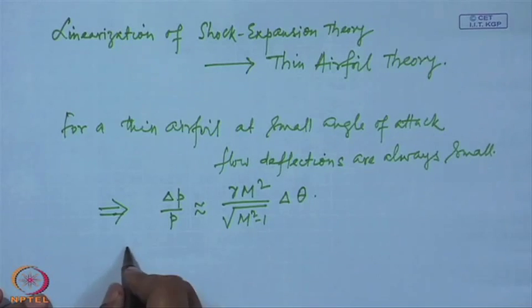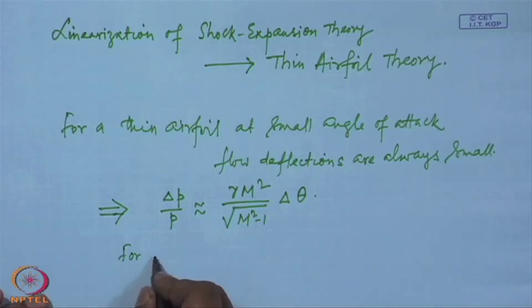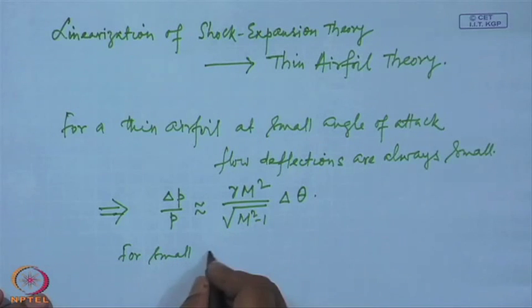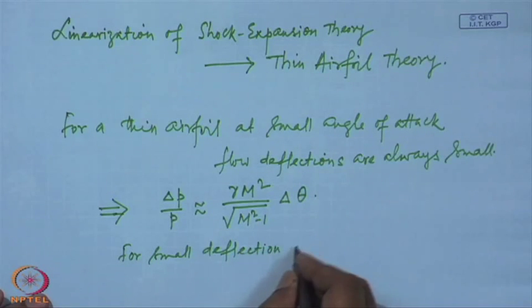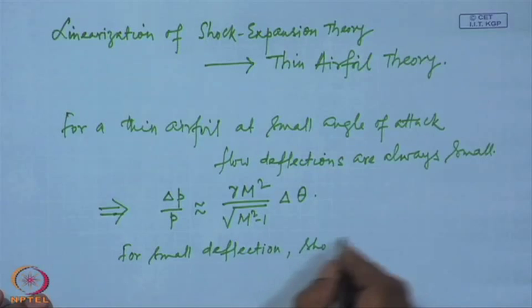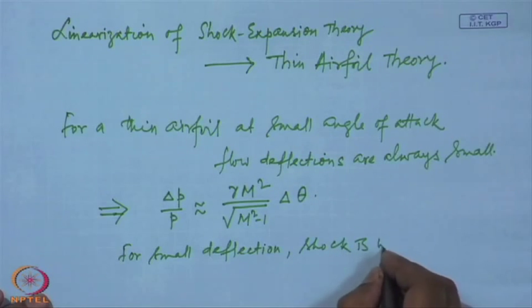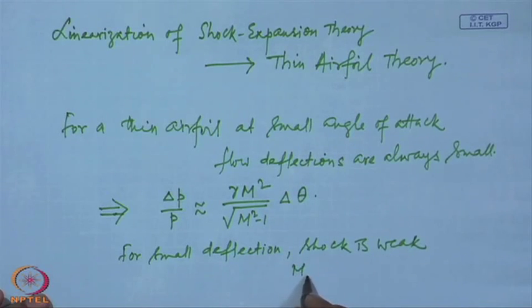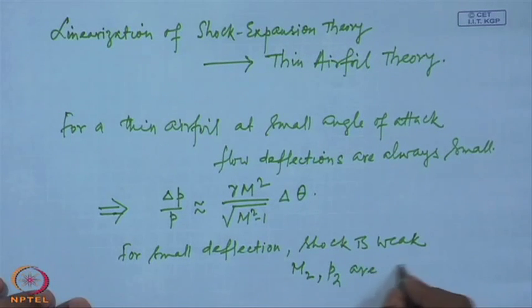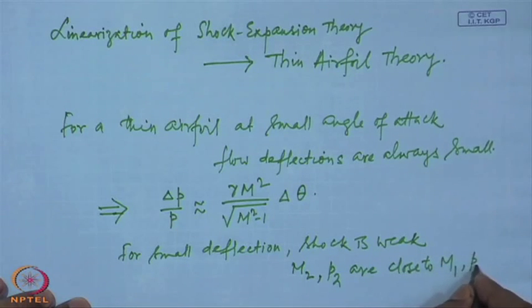And for small deflection, the shock is weak and M2, P2 are close to M1, P1.